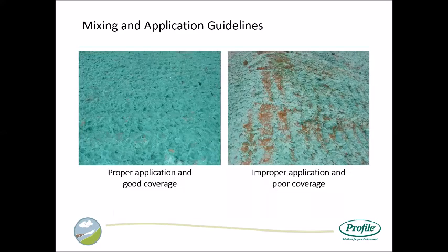Another issue, I mentioned cat tracking, how we like to see those cat marks going perpendicular to the way water leaves your site. It acts as little water bars to really slow the movement of water down your slope, and also increases infiltration on your site. We need to make sure if we're using these practices that we're getting good coverage on those types of slopes. So making sure you have 100% coverage is really vital. If you see soil, it's not protected, is my rule of thumb.